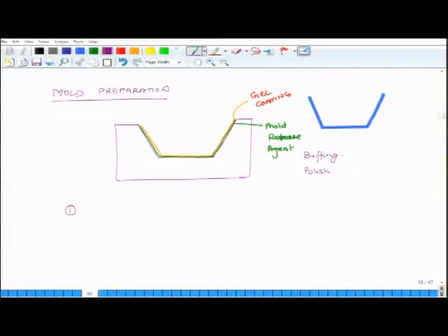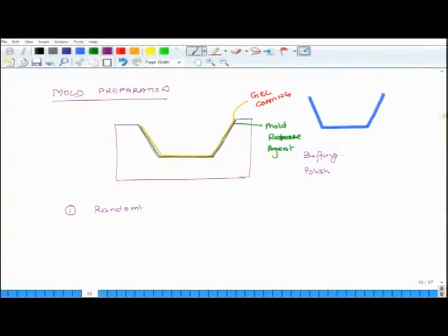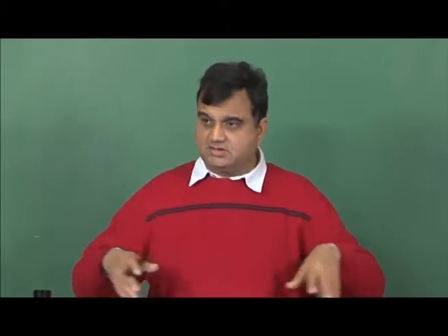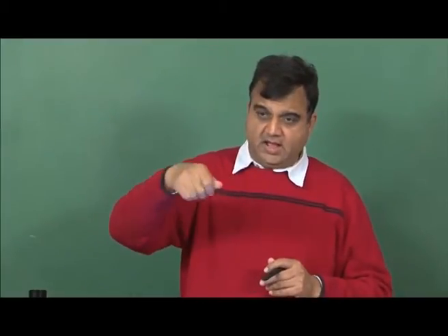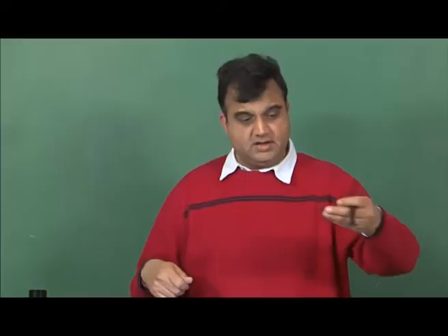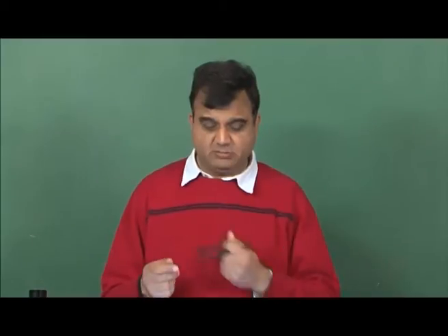So, if the fibers are randomly oriented, then what you do is you have small length of fibers, and through some nozzle you spray them, and because you are spraying them they fall in all sorts of orientations, and you keep on spraying it on top of the mold, and while you are spraying it on top of the mold through another nozzle you also spray matrix in fluid state simultaneously.